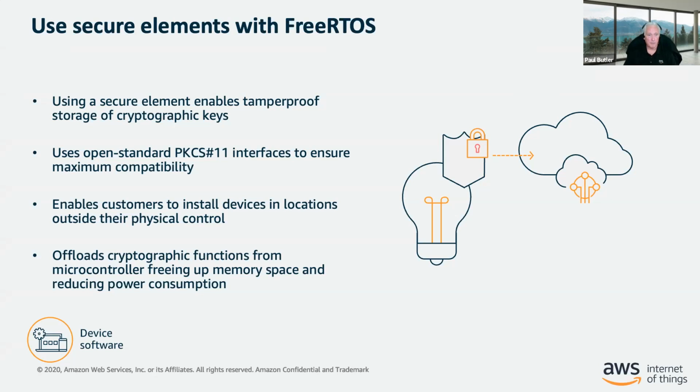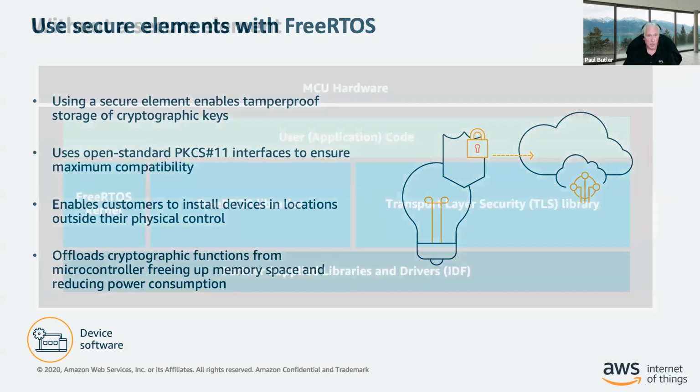They provide tamper-proof storage of cryptographic keys, and they also provide some other crypto functions, but your private keys and things like that are not exposed and not accessible. Only through this interface can you sign something, or validate something, but you never have access to the keys themselves. And that's one of the purposes of these secure elements.